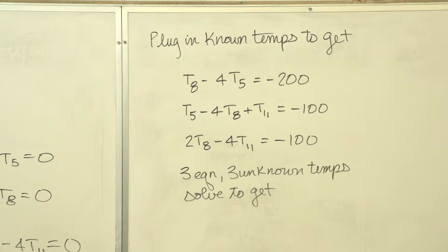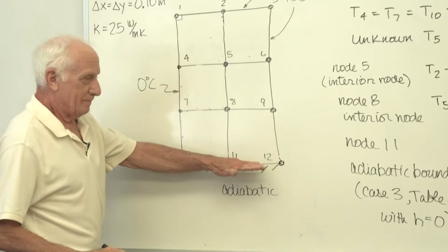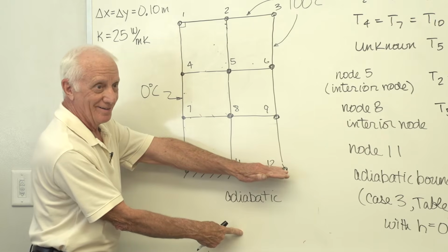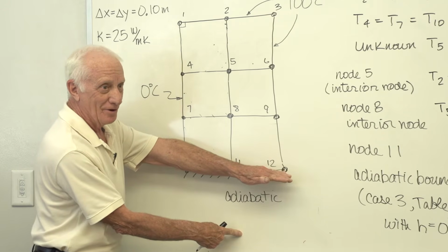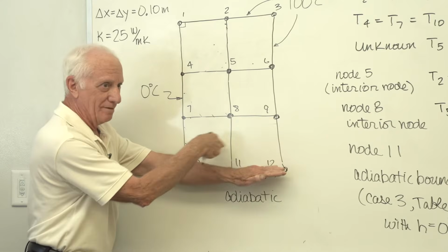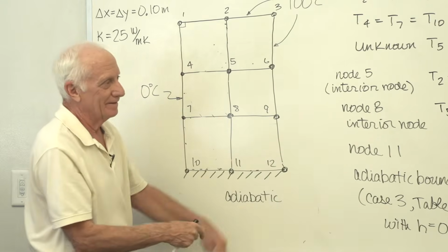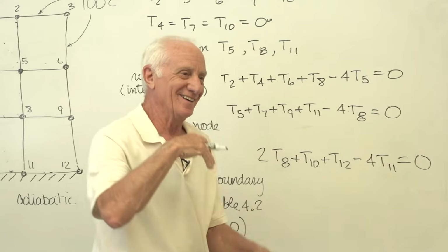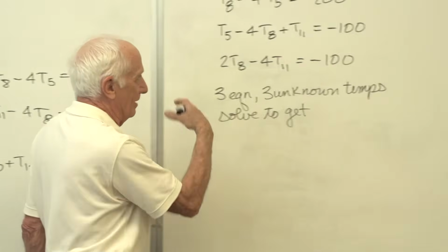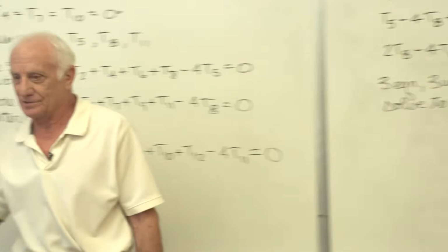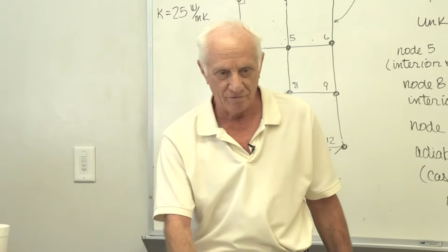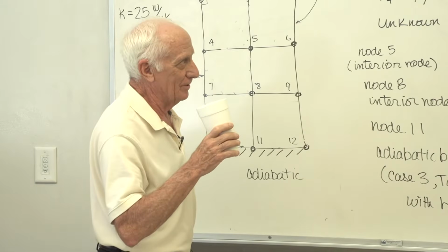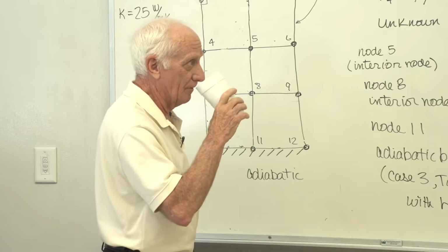Okay, yeah. Adiabatic wall behaves like there was a T8 here and a T8 down here. That's why. So now add your 4 neighbors together: T8 plus T10 plus T12 plus T8, 2 T8s. It's symmetrical about the adiabatic wall. Now you solve it, Excel matrix inversion, or on your TI with the solver function or whatever. So it's pretty simplistic. There's 3 equations, algebraic, 3 unknowns, solve for them.